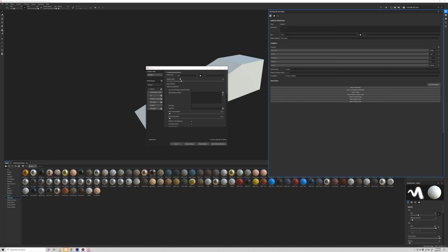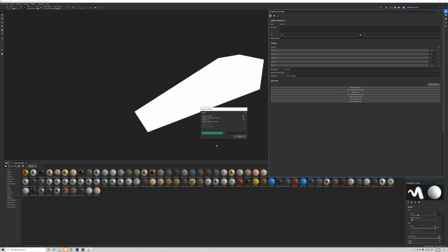Okay, so 1K, and I don't need to do a whole lot more. I can tick this option, use the low poly as the high poly mesh. So what that means is I haven't made another mesh that's got a lot of detail that I'm baking onto the low poly. I'm just using the same mesh. In other words, I only have one mesh. Baking is a whole other topic that's a bit more advanced than a beginner tutorial. We can look at that later. So I'm not changing anything else. I'm leaving all of these settings. I'm clicking Bake Selected Textures.